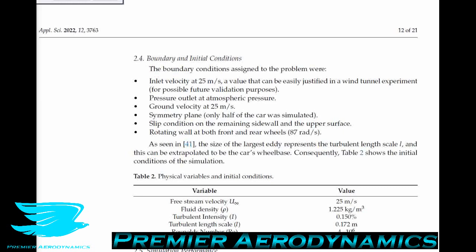The reason I say this is interesting is because, given their workstation, they could definitely have increased the fidelity of their model, even possibly switched to transient, because with this workstation setup, they could go to 15 million cells and the solving time would still only be maybe 3 days. As it stands, the solving time for the simulation was probably an afternoon.